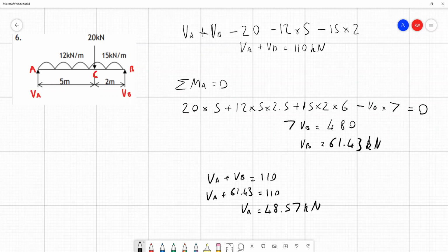So we started off at the top, just indicate this with a little green dot start up here. This is the sum of all of our shear forces. So we know that we have VA and VB. They're our support points in our beam. So they're going to be our upward forces reacting to the downward loads applied. And that there's 3 downward loads we need to consider. So this was a little bit different with this question is that we have different values for the uniformly distributed load in different sections of beam, but we'll highlight where each force comes in.